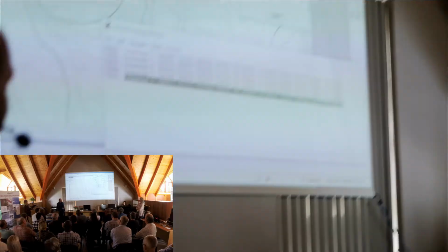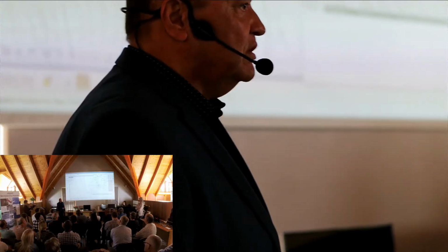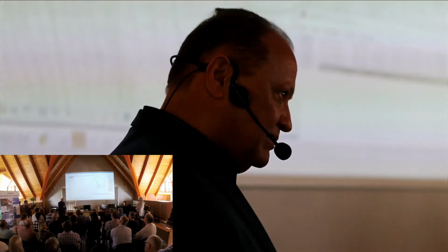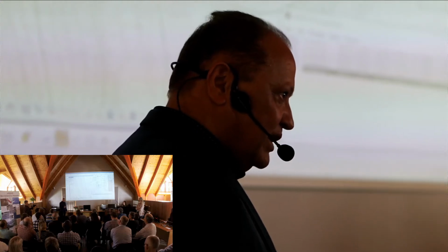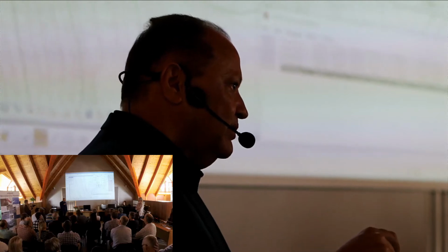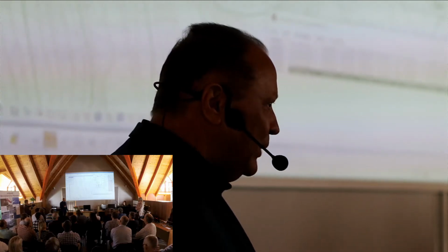Yeah. The nodes on the contour, I presume they've got nothing to do with the crossings of the triangle lines. So it's to do with the smoothing. It depends on how you set up the automatic creation. So when you set up the creation, if you change all of these to zeros and you give it a zero smoothing factor, your contour is going to go exactly through that triangle's edge at that point, and you're going to get a node at that point. An exact node at that point.